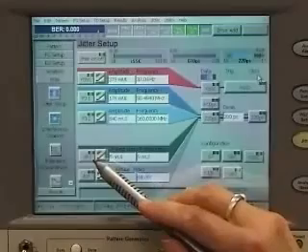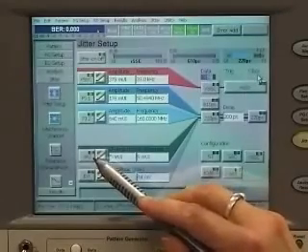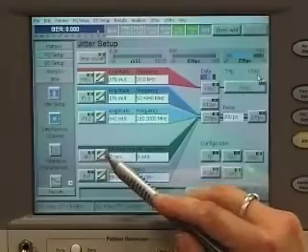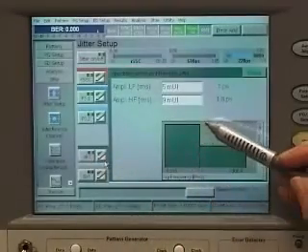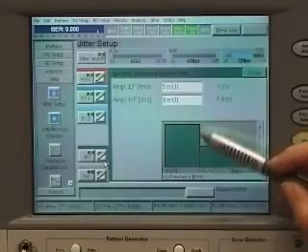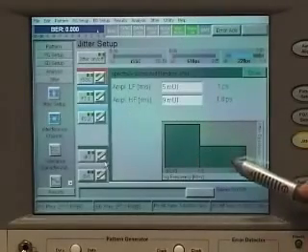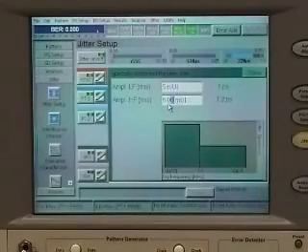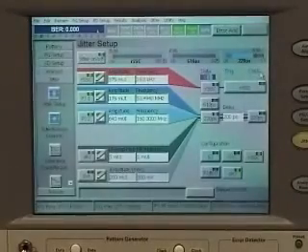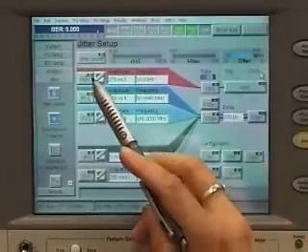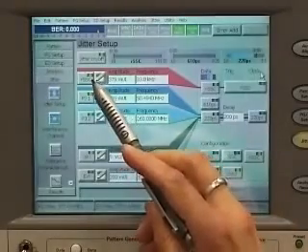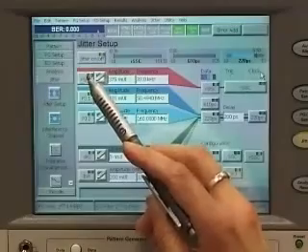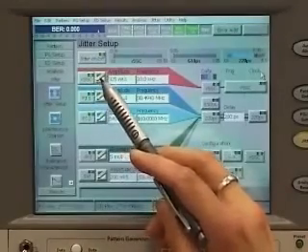If you have to test a PCI Express Generation 2 device, you will need the spectrally distributed RJ. Here you can enter the different magnitudes of the low-frequency modulated and the high-frequency modulated jitter. Here, this is residual SSC, which is commonly used in PCI Express Generation 2, especially for add-in card test.